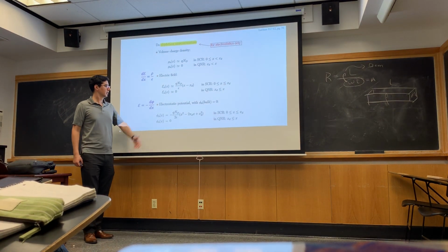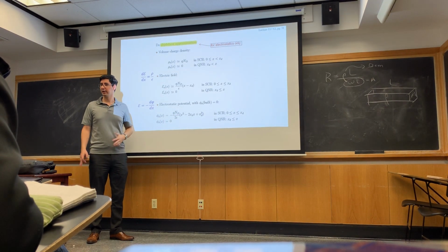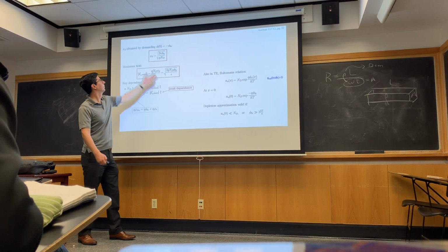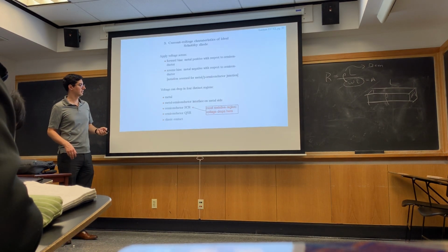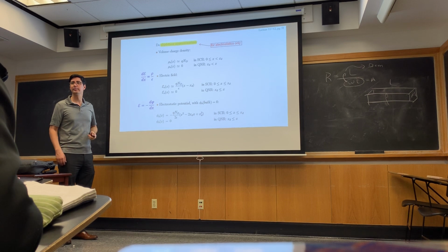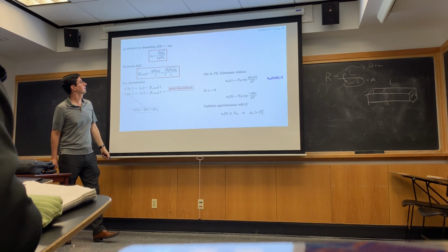Okay? So that quantity has to equal phi bi. So let's solve for xd. Bam. I had something that was xd squared times a constant equals phi bi, so then xd equals the square root of phi bi times the constants.